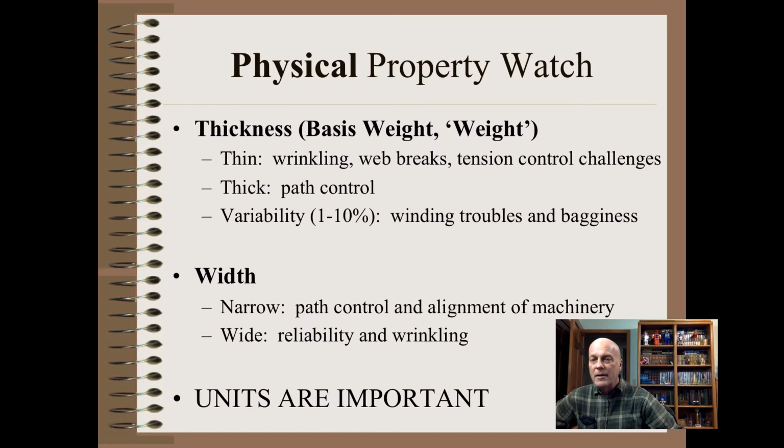Again, units are important. Here again you can see some truly strange mixes. For example, the standard basis weight measure in nonwovens and textiles in the U.S. is OZY. That stands for ounces per square yard. And paper weight is measured in pounds per ream. And that ream might be 1,000 or 3,000 or perhaps some other number of square feet, depending on which paper grade you're talking about. The metric equivalent is much more sensible in many ways and is usually simply GSM or grams per square meter. Even here, we have mixed units because it should be kilograms per square meter or grams per square centimeter. Confusion like this allows a degreed engineer to work but more slowly. However, it makes even the simplest math untrustworthy by almost everyone else.